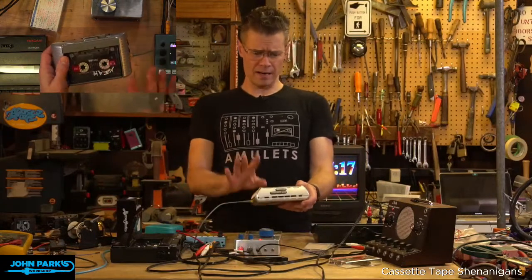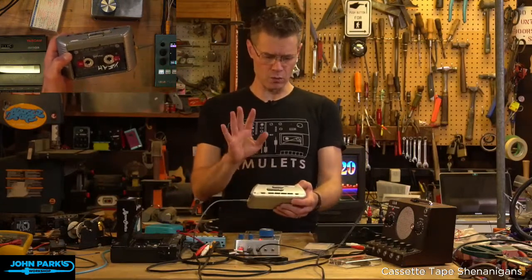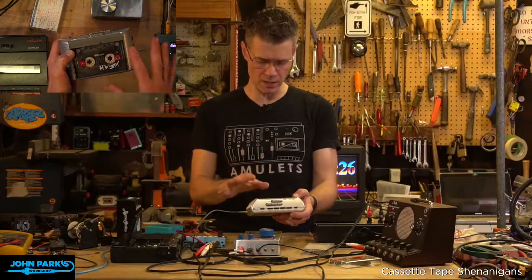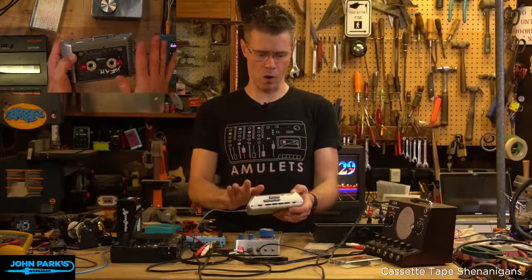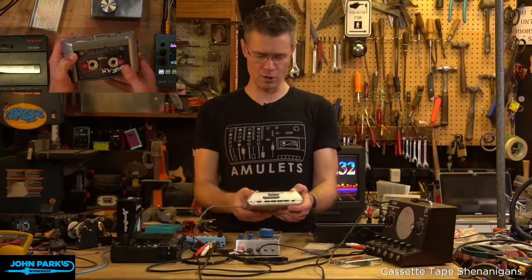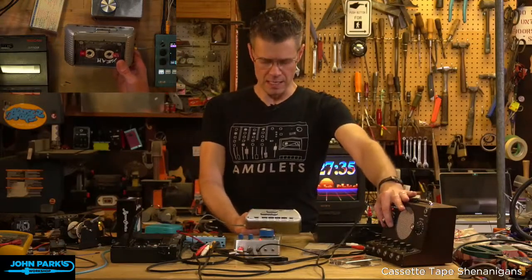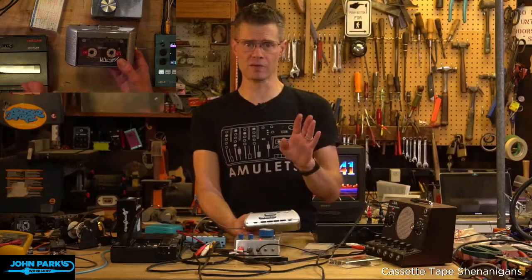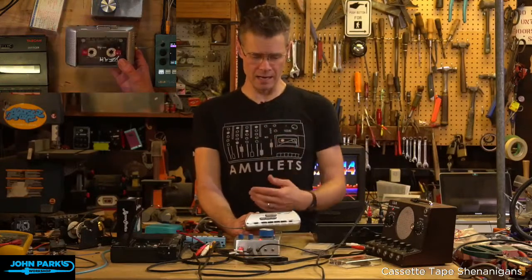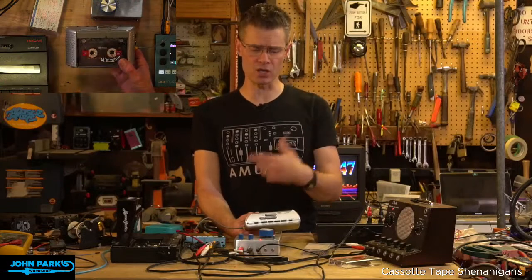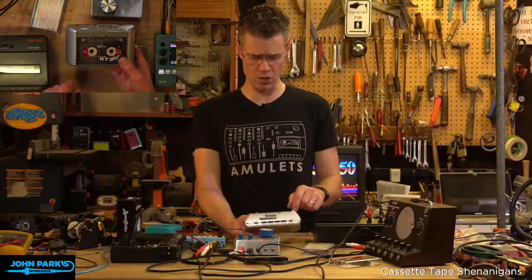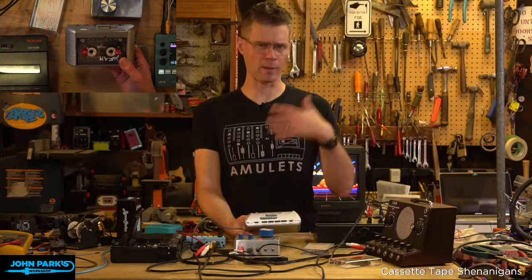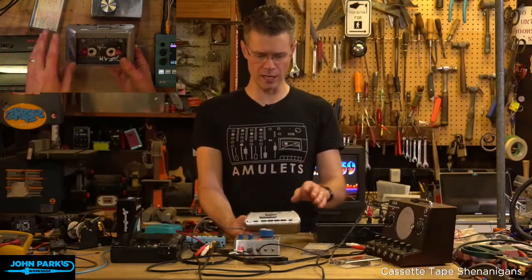This is just a lucky find, they don't really make these anymore. I had to replace the main belt in it. It had just turned to goo, which is kind of the problem. If you want to get a used Walkman, generic term I'll use it as, on eBay or other places, it's not a bad idea to look for ones that say they are tested and work, because if not, you will have a job ahead of you of getting inside. Sometimes it's a pain to get where you need to get. Sometimes you have to take a lot of things apart to get a new belt on there. You also have to buy a pack of cassette belts. You don't want to try to use hair bands or rubber bands or anything. You've got to get the right stuff. Rubber bands will just give you trouble and stretch and turn into goo again.